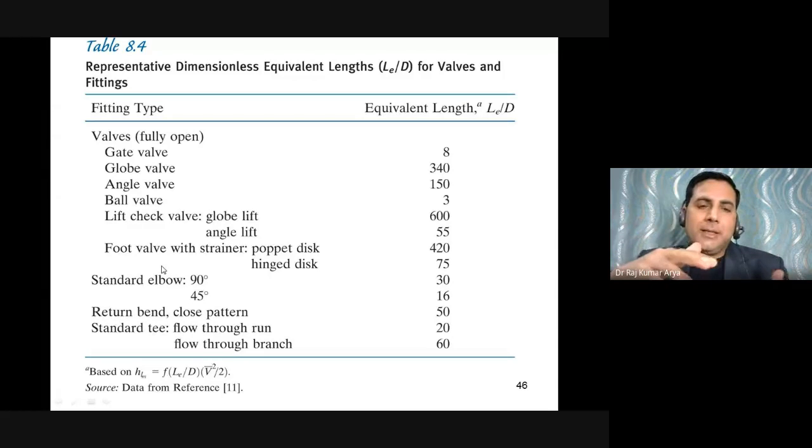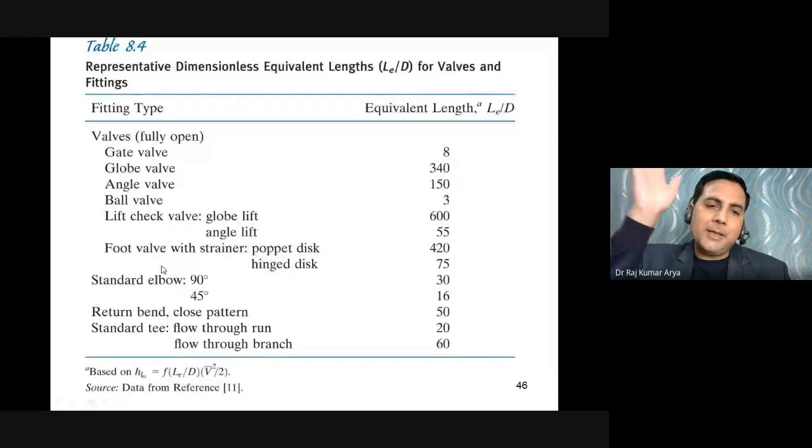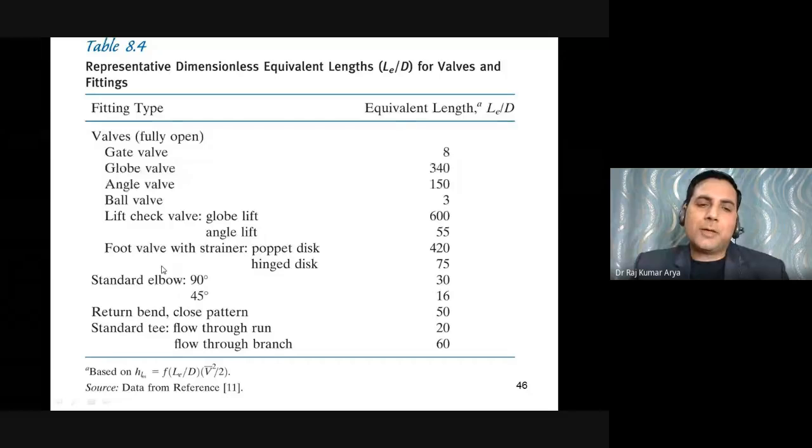Initially, when you lift the water in the beginning, you apply a heavy suction force or suction pressure so that it can lift the water from the ground level. After that, you keep a valve fitted there all the time. Whenever you turn off the pump, that valve immediately shuts, so it stops the backflow of water. So this is the purpose of the foot valve. I will show you how it works also.